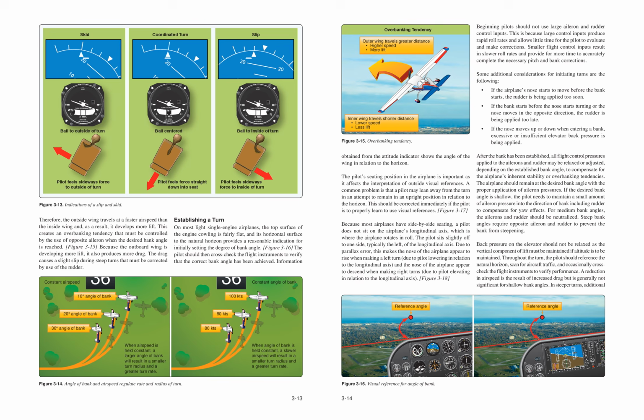Figure 3-18. Beginning pilots should not use large aileron and rudder control inputs. This is because large control inputs produce rapid roll rates and allow little time for the pilot to evaluate and make corrections. Smaller flight control inputs result in slower roll rates and provide for more time to accurately complete the necessary pitch and bank corrections. Some additional considerations for initiating turns are the following.